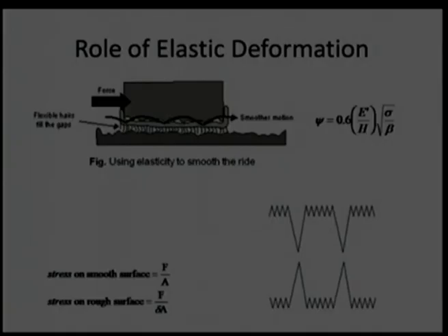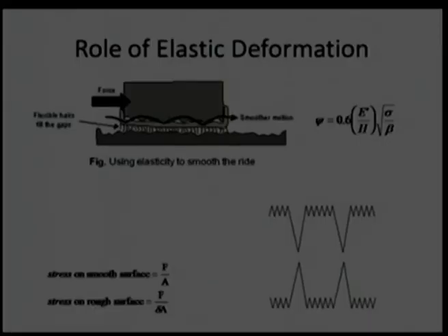But when we talk about tribological components, we need to take only a fraction of this area. We know very well the whole area cannot be in intimate contact due to the asperities, and because of the asperities, the effective area or real area will be much lesser. 99%, this area is lesser than 16% of the total area. As it is lesser than 16%, I can say the effective stress on the machine component will be almost 6 times compared to what we calculate with the ordinary formula.